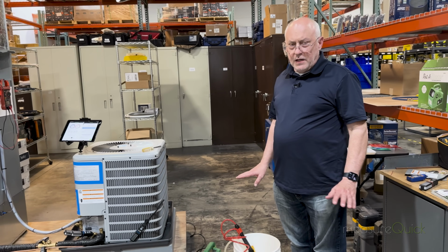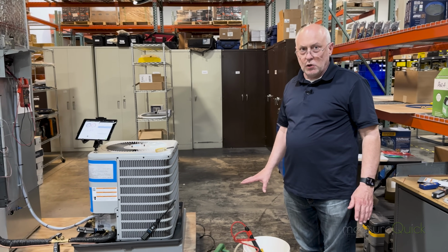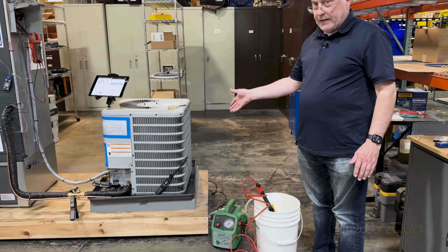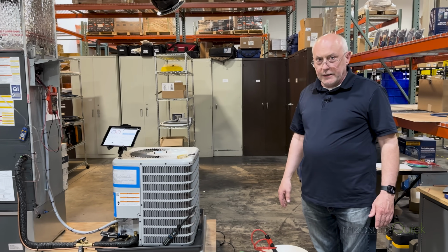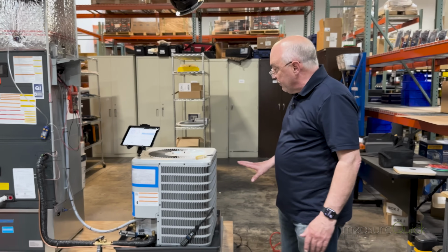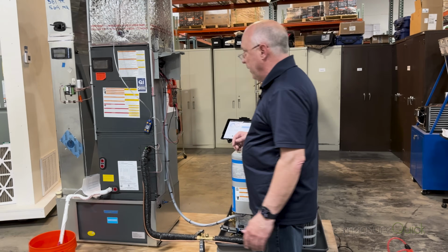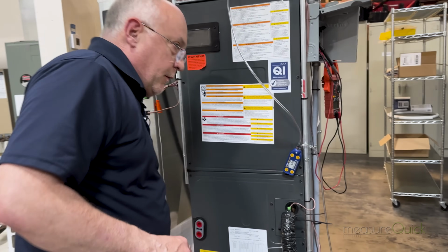All right, so we just got done cleaning our coil with a Subcoat Portablaster. It's a really slick tool. If you haven't seen one, it's actually worth looking into. It's great for inside like this where we can just use a 5-gallon bucket full of water and clean our system out. We got this thing drying up, and while it's drying, we're going to go over here and measure airflow real quick with a manometer to make sure we're in the right range.